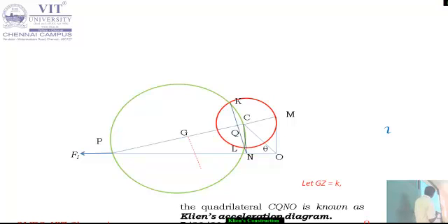So what we have to do is consider this as a two mass system. For that, I extend the line at right angle to the connecting rod and fix a point Z here. How can I fix the point Z? By using this relation: let GZ be equal to K. What is meant by K? K is the radius of gyration.